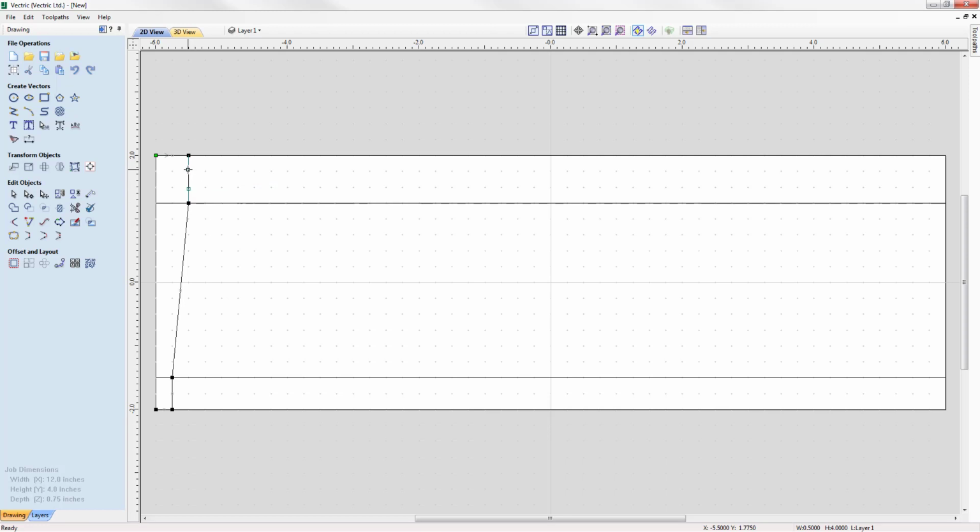I'm going to take this control handle, snap to that point there, take this control handle and snap to that point there. Okay, so I'm happy with the top part. So here I'd like to turn this span into a Bezier, so let's press B on the keyboard. You can see now I have access to these control handles to really transform the shape of this span here. So I'm just going to take that node and we're just going to pull that out somewhere like that.